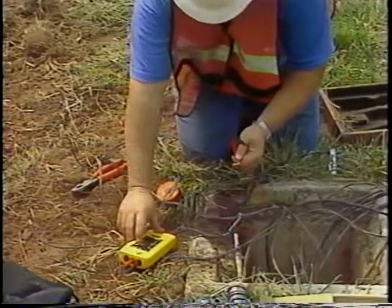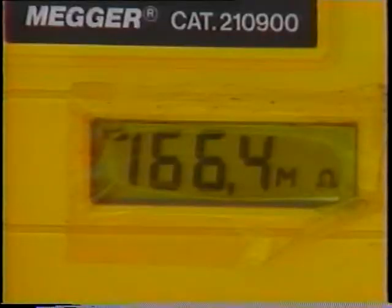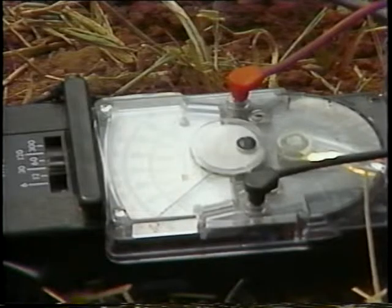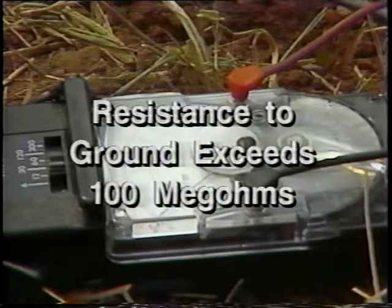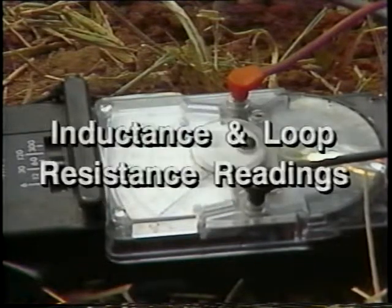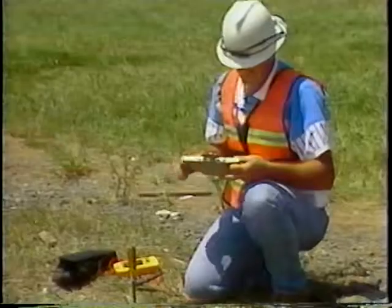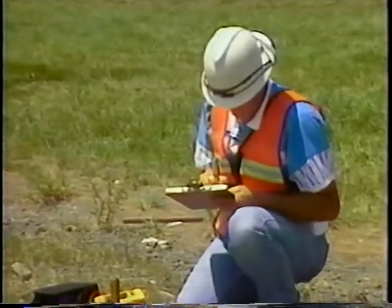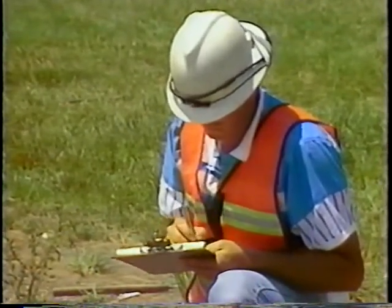Applying a 500-volt megger between each end of the lead wire and the nearest electrical ground should produce a reading of at least 100 megohms under any condition. The loop installation is acceptable if, when measuring induced voltage, there is no deflection of the voltmeter pointer, when the resistance to ground of the loop exceeds 100 megohms, and when both the inductance reading and the loop resistance reading are within 10% of the calculated values on the wiring diagram. These metered values should be written on the wiring plan or on an inspection report for future testing and maintenance.